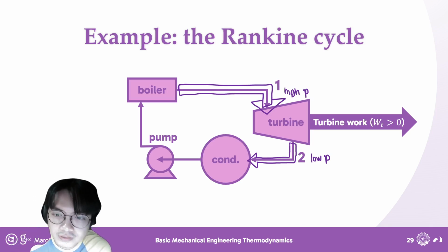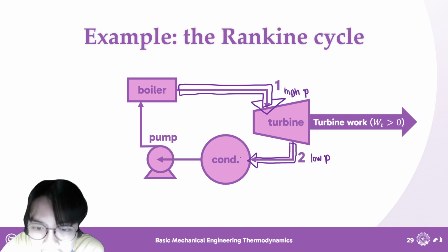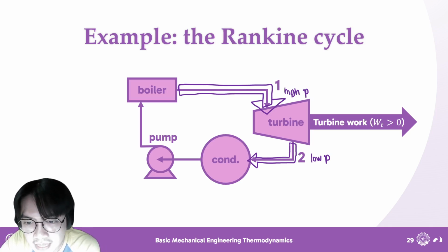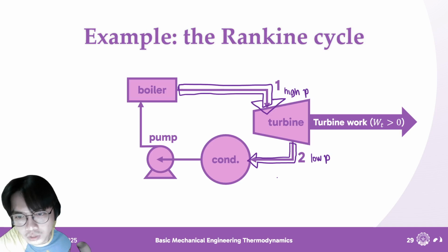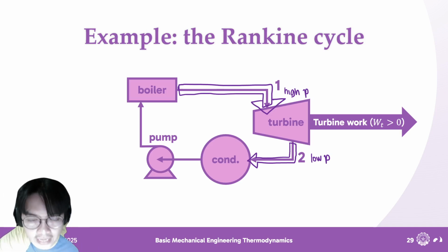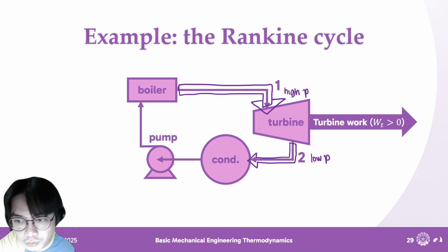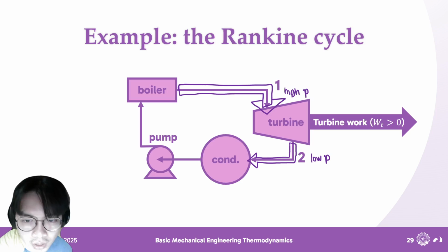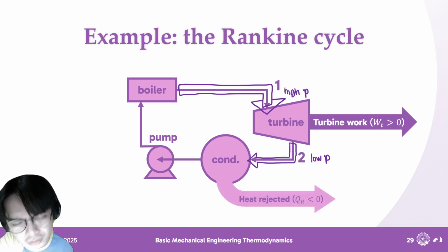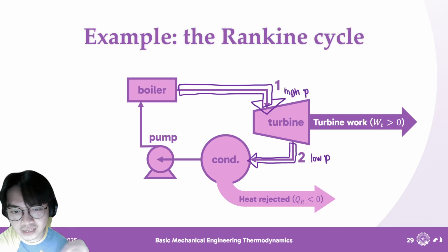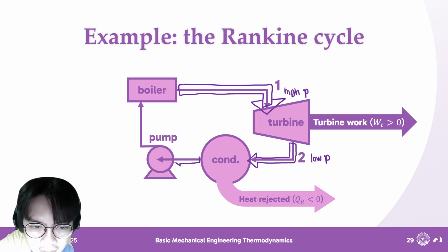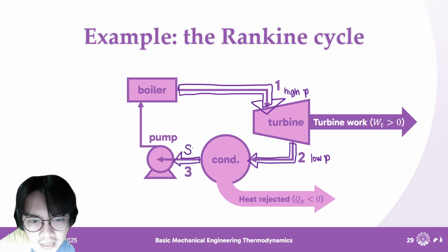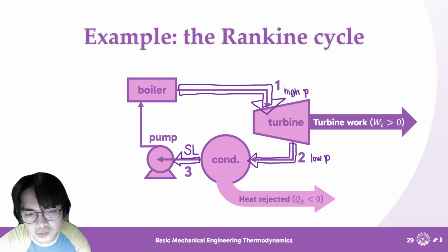And so what do you need to do to turn this steam into liquid water? Well, you condense it via a condenser. What will happen is that this steam, which is still quite hot, but is no longer at the correct pressure, is going to condense. At the exit of the condenser, your fluid, state 3, is supposed to be saturated. In other words, it's just going to be a liquid. And moreover, what does a condenser do? Well, it removes some of the heat from state 2 and puts it out into the atmosphere or to wherever, actually. What a condenser does is basically throw away the heat from the steam so that what comes out at state 3 will be a saturated liquid. Always, guys, always. Saturated liquid always for state 3.